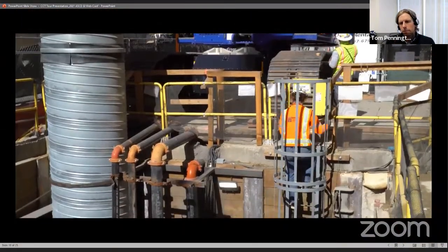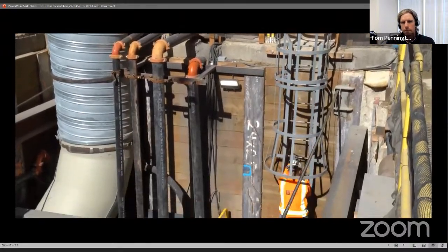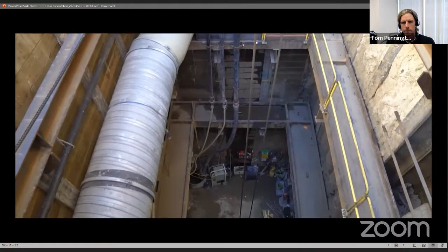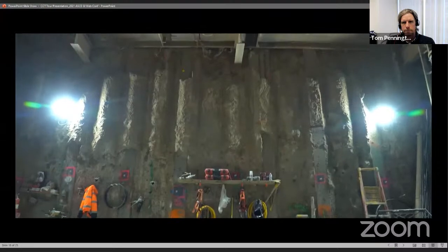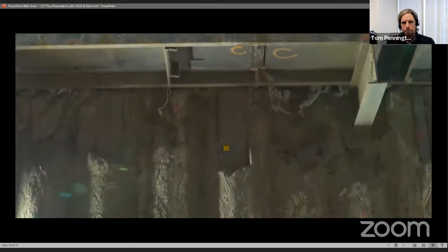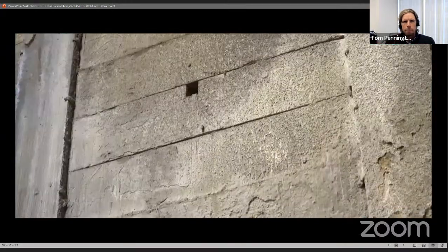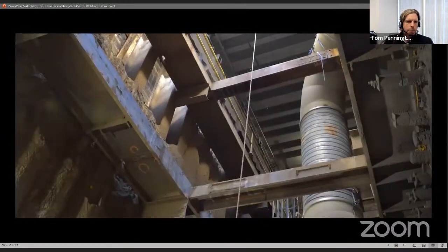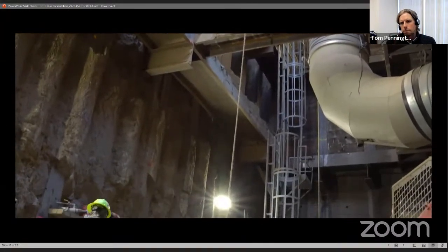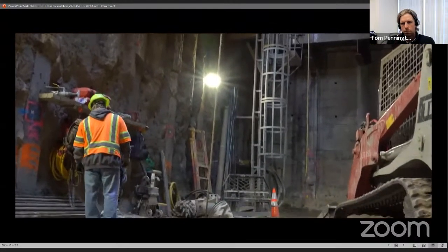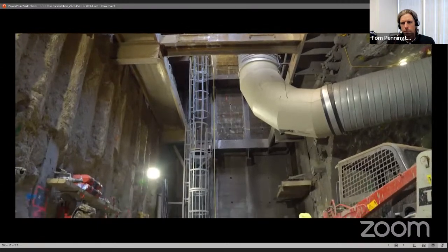Construction of the tunnel began with excavation of the starter shaft, excavated at the existing sidewalk adjacent to the central jail. The building side of the shaft is supported by a secant pile wall, and the remaining 3 sides are supported by soldier piles and wood lagging. The shaft required 3 levels of bracing and a reinforced concrete floor slab to withstand the central jail foundation and ground loads while limiting wall movement. Once the shaft floor slab was placed, the lowest bracing level was removed.